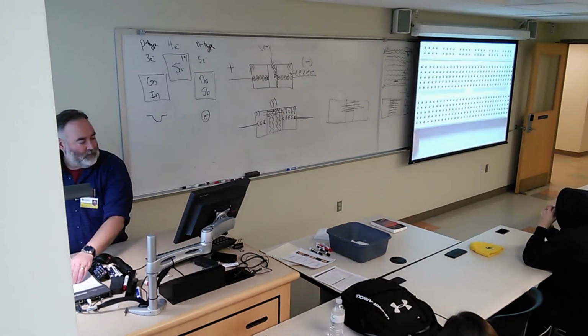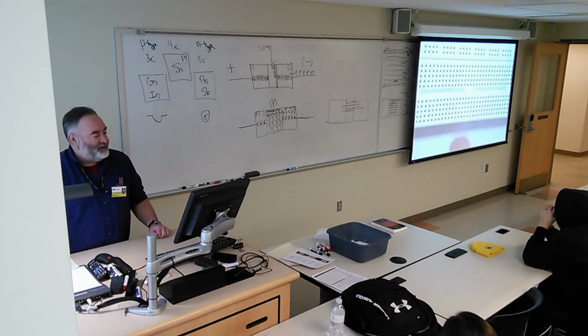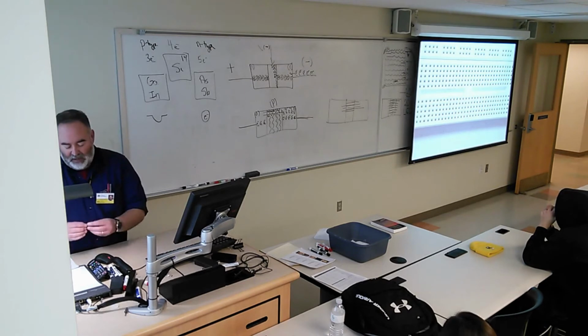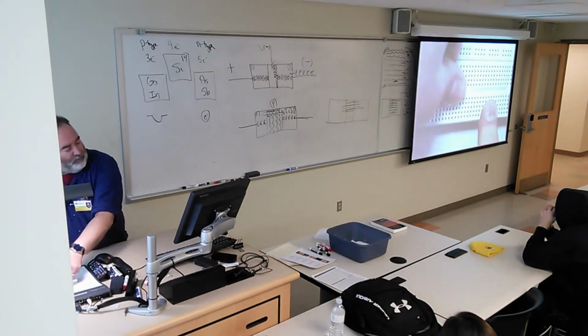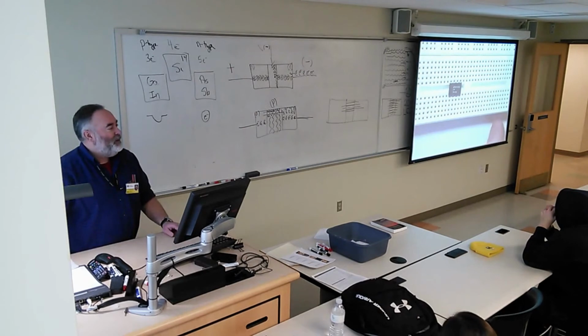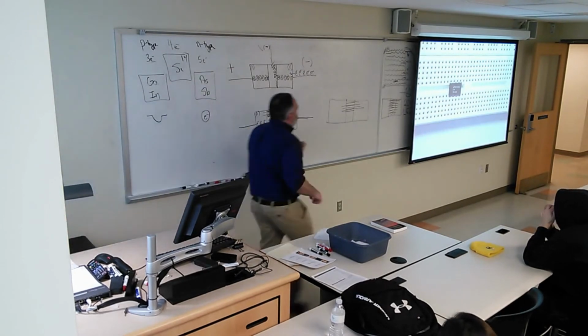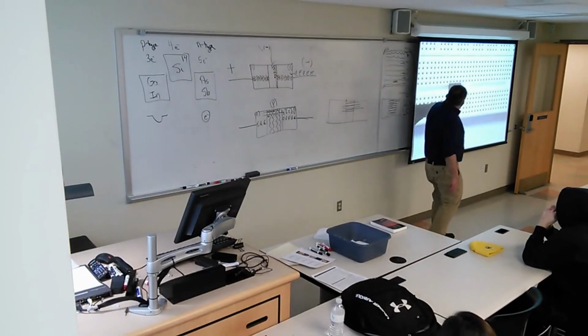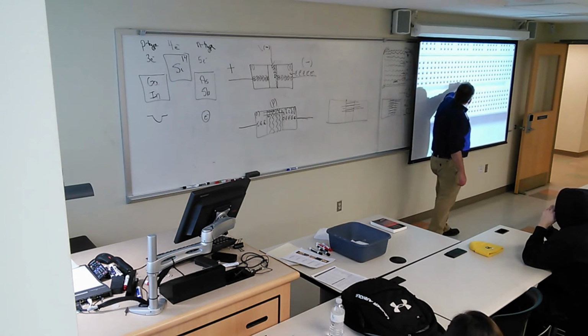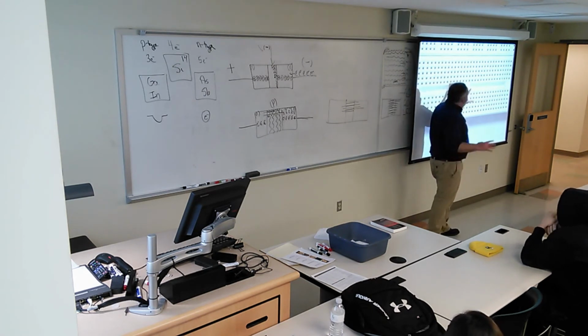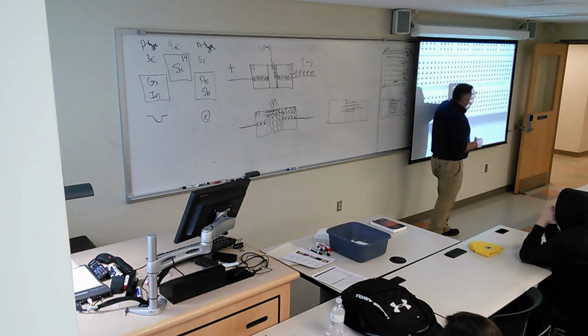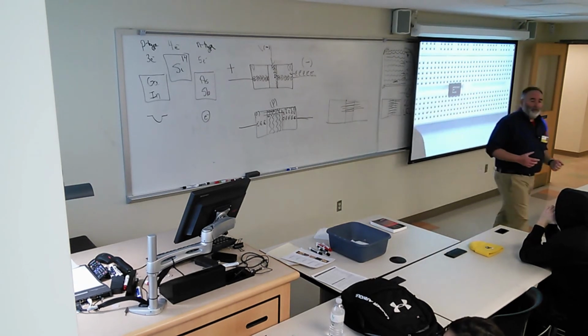Here's our breadboard. Remember, the top is not connected to the bottom. If you take this chip and you take those 4 legs and put it like that, now it's ready to be wired up. Okay. What we can do is we can put wires to these individual 4 little pins by putting them in any of these 4. And we can put wires to these pins on this side and putting that 4. And then we can wire into this giant circuit that's inside there. This little integrated circuit as a whole works as an amplifier.